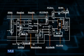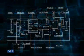Now let us have a look at the 4th cycle. During the 4th cycle, as we mentioned earlier, the 4th cycle is the memory operation cycle, and this cycle is used only in case of load and store instructions. However, different types of control signals are to be applied for the load instruction, and different control signals are to be applied for the store instruction. So let us first of all consider the load instruction.